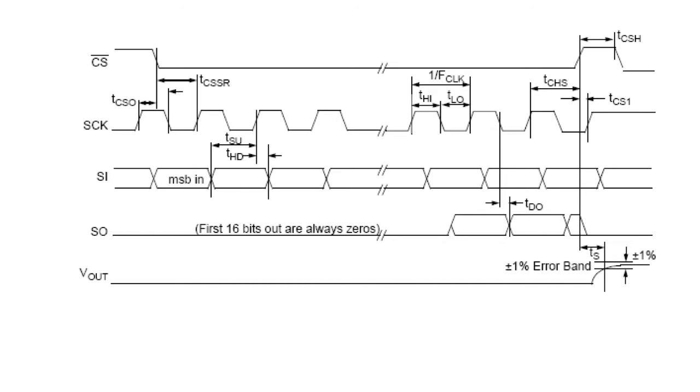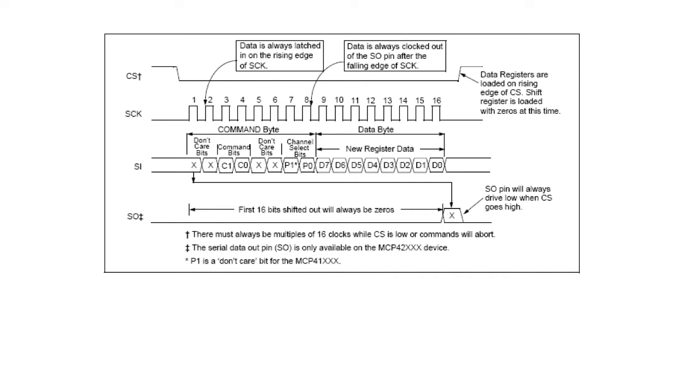And this is probably too much detail by half for a timing diagram, but it essentially shows you that you have to take the inverted serial chip select and assert it low in order to select the chip. And then the serial clock comes in and then proceeds to strobe in the data as it comes in through the serial input. So if data is latched on the rising edge, and you can change how that works by using the serial control register, you can effectively determine exactly when the input signal is going to be sampled.